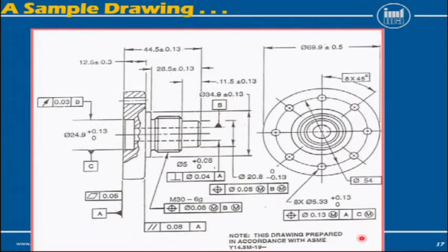So, in a GD&T drawing, the datums need to be indicated in the proper manner, and the primary datum should be controlled for form, secondary datum should be controlled for orientation. Then you add the other controls as required, could be position, could be runout, concentricity, etc., etc.